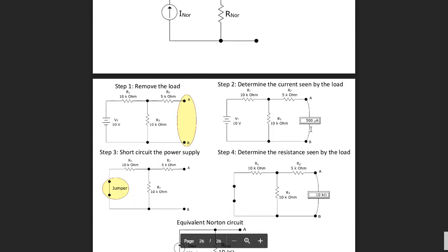Now we have the same process for that. In the above Thevenin's theorem, we find the voltage across that load, VOC, and here we have to find the current through that load, which we can also call ISC. VOC stands for voltage of the open circuit, as we remove the load and find the voltage there by using mesh or nodal analysis or any other technique. It is up to you.